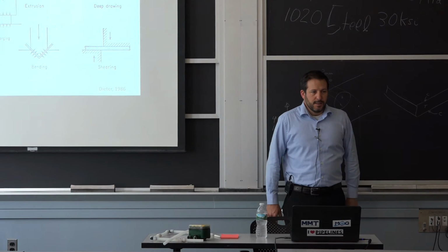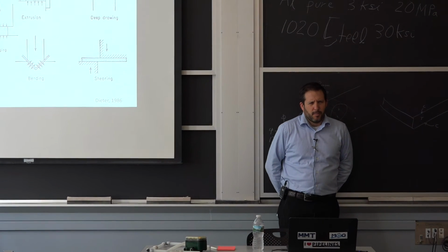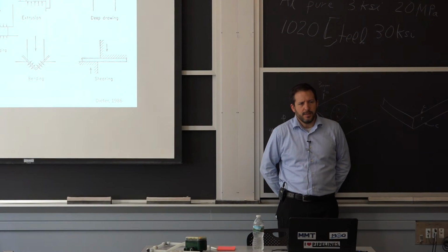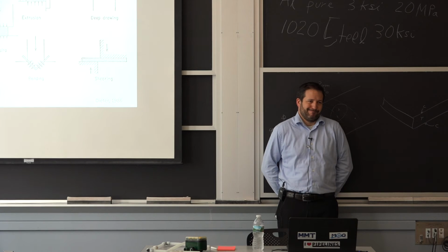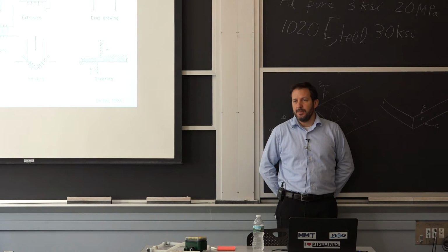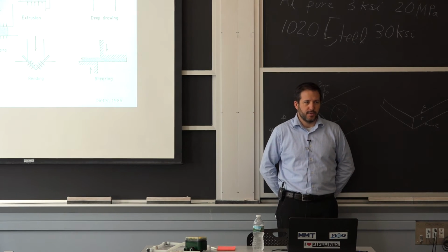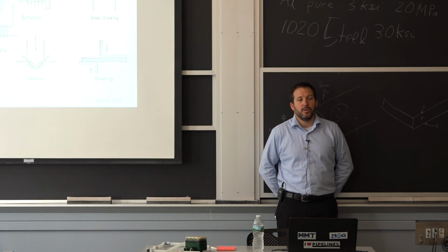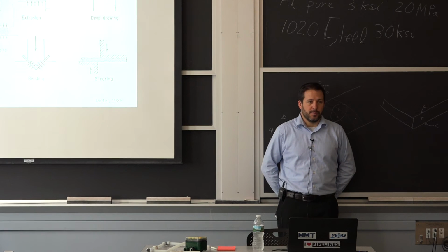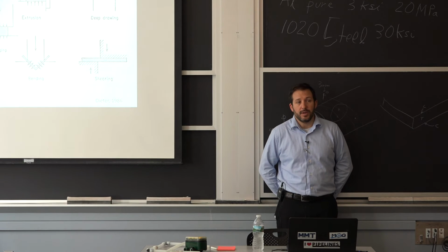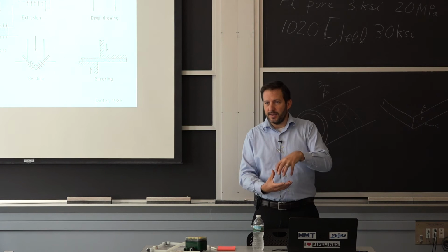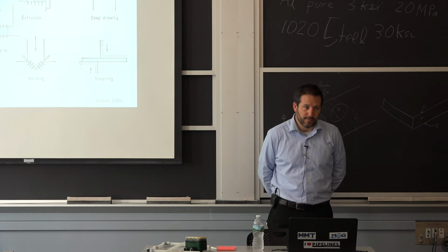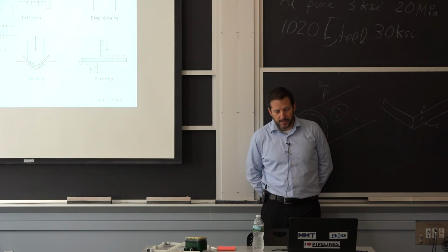The reason they did it for this one is this is oil or gas piping, so you don't want any fitting to be brittle. If it was water, it's not as interesting, but a water leak is not as bad as oil and gas. That's one reason why this complex shape wasn't cast but forged. It's a lot more expensive. You can think of all the tooling to heat up and then come and hammer it down to that shape. There's a lot of forces involved. It's very dimension specific.